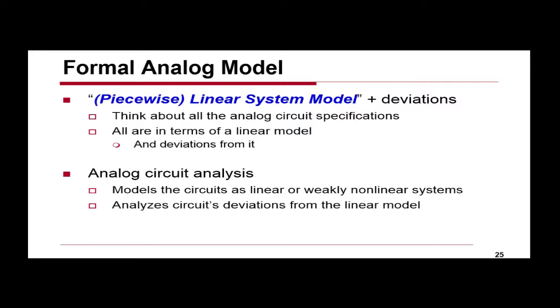Now, I will say that the reason I believe this is a good idea is if you think back to any of your analog design courses, how do they teach you to analyze analog circuits? Small signal analysis, right? How do they give you specs of analog circuits? They're all small signal specs. They're all doing the piecewise linear thing. And they also give you distortion. Sometimes you have to worry about deviations from the linear behavior. But that's the way every analog designer I know talks about an analog circuit. So we are already intrinsically doing that. We're just timid about it, I guess.